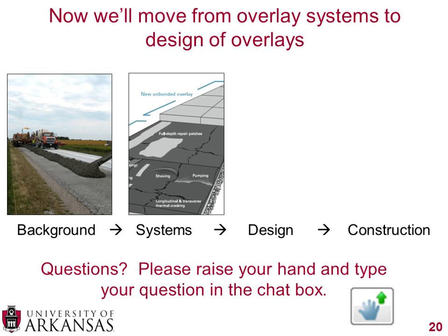And David, I'm actually going to get back to you on that, because it's my impression that on some of the more extensive distresses, they recommend a full depth repair. And ASR in particular, I'm not sure about. So I'm sure that there's been some research articles written on that, and I will get back to you on whether or not you need to do a full depth repair on ASR, or if that's something that can just be covered.